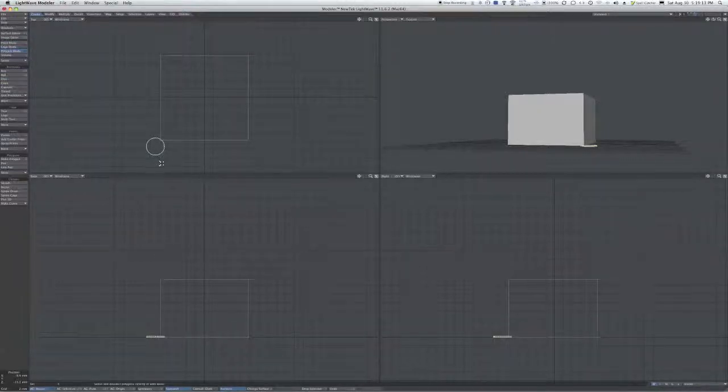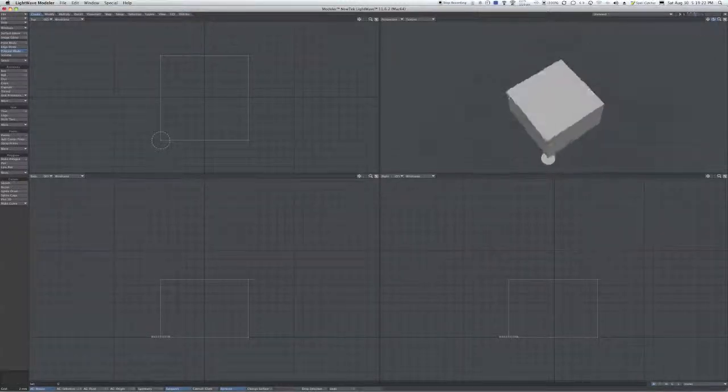So you put a little disc like this on each corner, and what that'll do is this will stick very well, and it'll keep this corner. It's usually corners that want to pull up first. Yeah, they may pull up and come all the way back to the middle, but it's the corner. If you can keep the corner down, you can keep the rest of the print down usually.